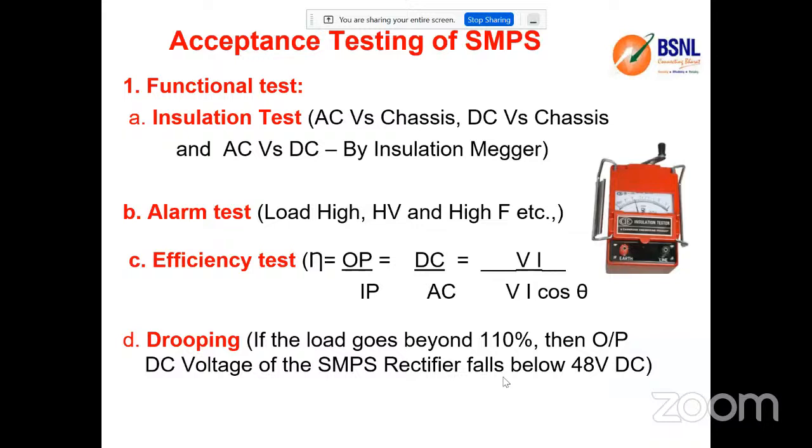like QC, quality check. They will test whether the power plant is perfectly installed and whether it is capable of handling the loads, so they will provide an artificial load. Before directly connecting to the telecom loads, they provide the artificial loads and verify the installations of both the AC and DC parts. They check all the other controls and monitoring parameters. Then they certify that it is perfectly fit for installation. That is what we call the acceptance test, or AT.